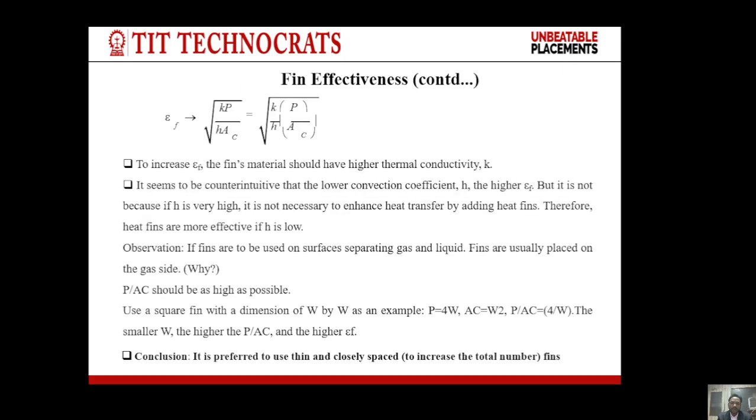So to make the effectiveness more, these are the parameters. The fin material should have higher thermal conductivity, or the heat transfer coefficient h should be higher. So these are the two parameters on which the effectiveness of fin will depend.